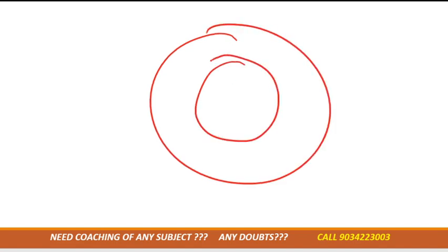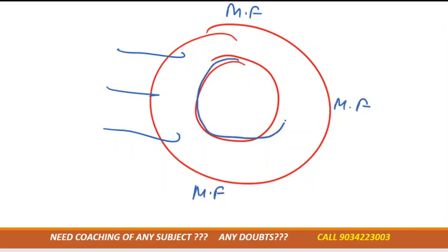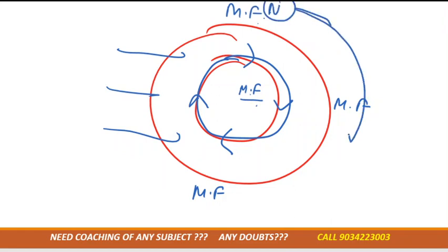Like this is the stator and the internal one is the rotor. Now you can see that the rotating magnetic field is produced on the stator. Suppose magnetic field is here, here, and here. So due to this magnetic field EMF is induced in the rotor, and due to the EMF there is a production of magnetic field, and these two magnetic fields interact with each other. Suppose here a north pole is generated. Now the magnetic field rotates, and the north pole will come here. And suppose on the rotor side there is a generation of south pole.